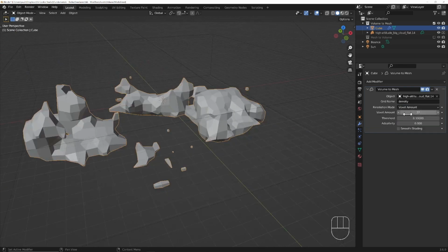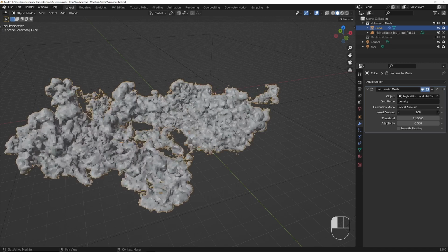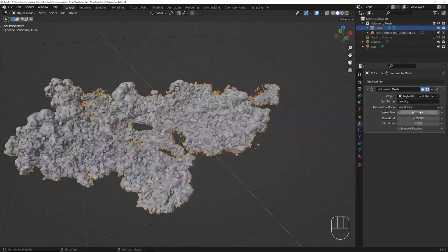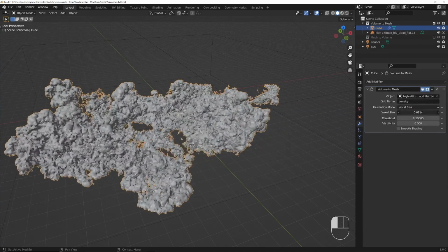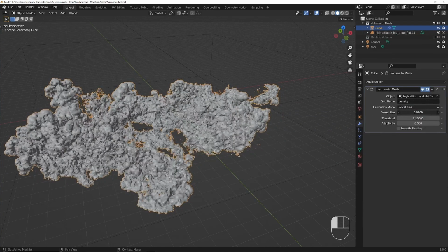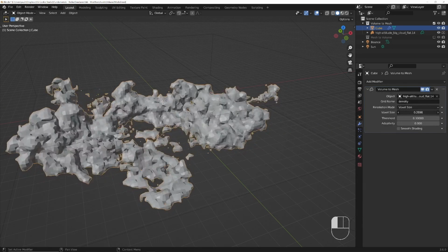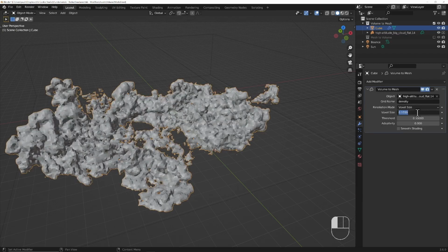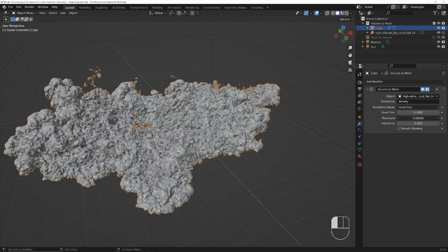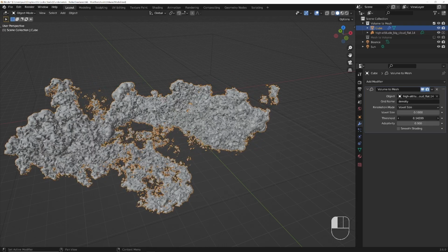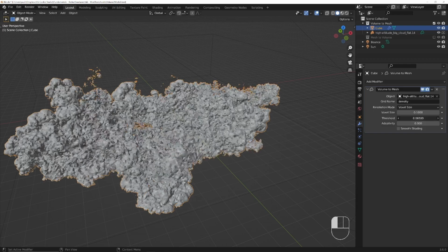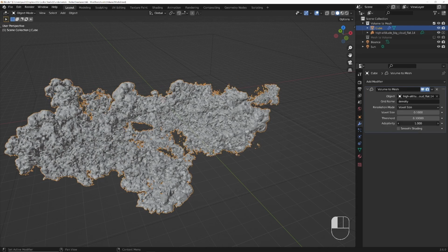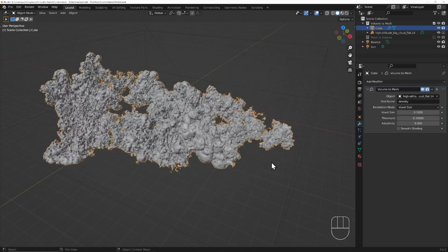The amount refers to the number of voxels that will be generated along an axis, and the size refers to the generated voxels' dimension. The fewer voxels that are present in a voxel amount, the lower the mesh resolution will appear, and inversely, the smaller the voxel size, the higher the resulting resolution appears. In both cases, the threshold and adaptivity work in the same way as they did for the grid resolution, by increasing or reducing the number of voxels permitted in the volume, and by reducing the amount of topology generated when it is not required.